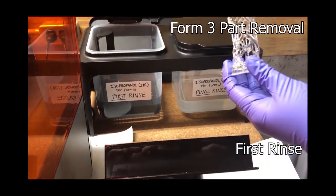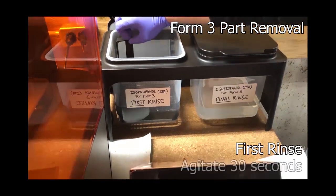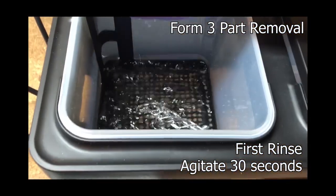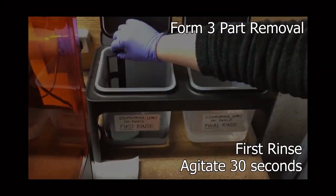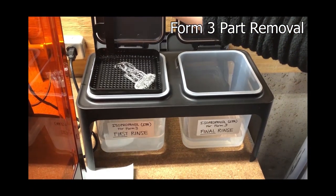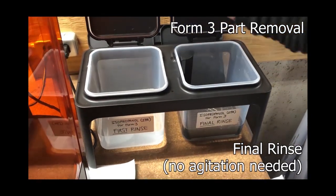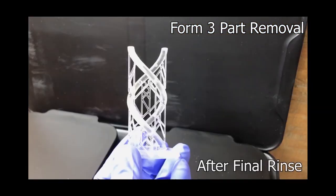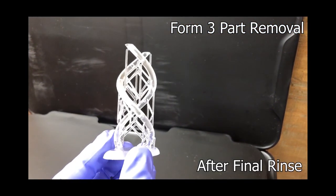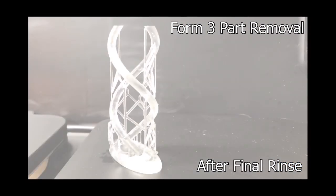Once it's out, I'm using the first rinse of IPA, and you have to shake, agitate this to try to remove the outer layer of the liquid resin. And then you move it and start the final rinse. So it's about 10 minutes. You can let it sit there for a little bit longer, but after a little bit of just drying in the room, you get the final print with the supports.